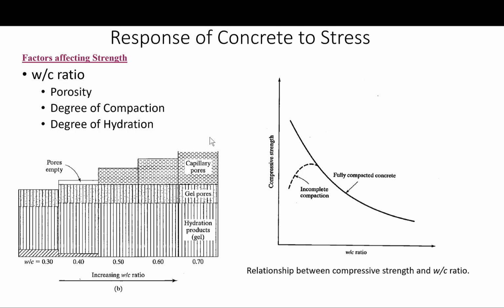So one example of the limitation of the water cement ratio is illustrated in this figure right here. Okay, concrete that is not properly compacted will contain large voids which contribute to its porosity. So at lower water cement ratio, where full compaction is difficult to achieve, Abrams law ceases to be valid. The point at which this occurs depends on the methods of compaction that are employed in that particular concrete.